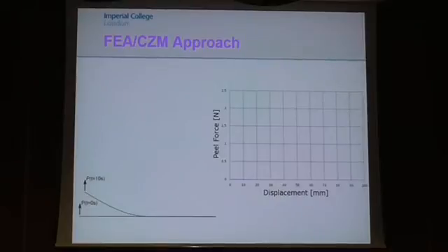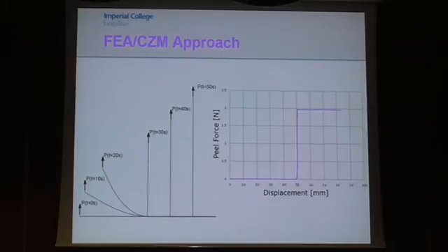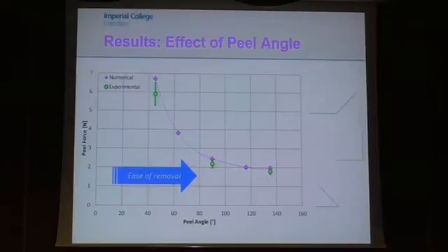And here you can actually see the force displacement graph at different points during the peel test. You can see initially it bends until I get a steady state force. So it seems as though my peeling model works, but naturally I need to go into the lab to actually validate it and make sure that my model is correct. So purple dots are what the FE model predicts. Green bars are experimental. I'd say it's a pretty good match.